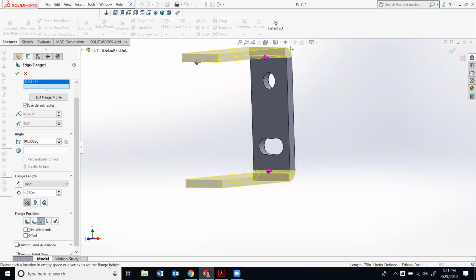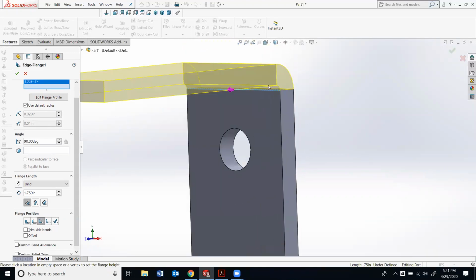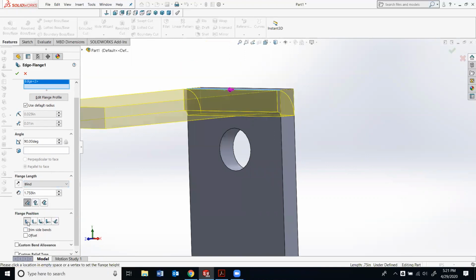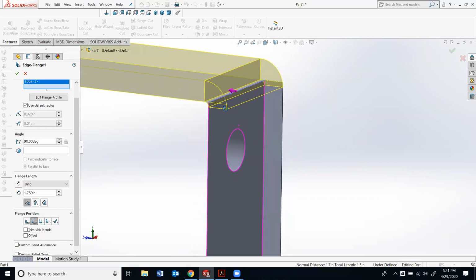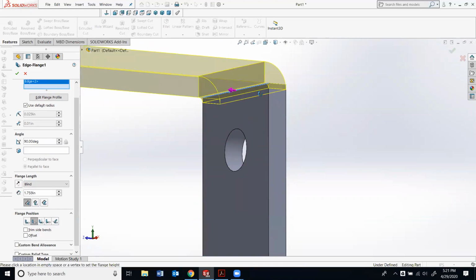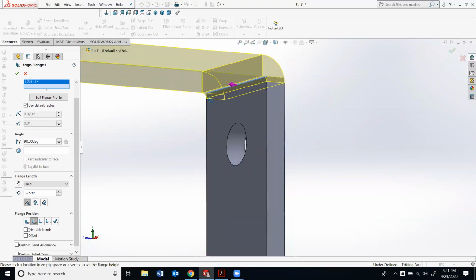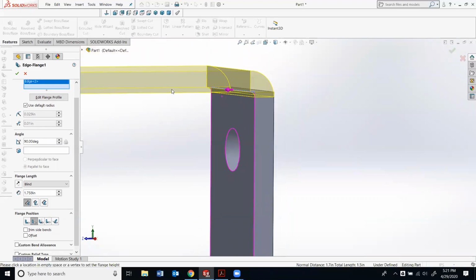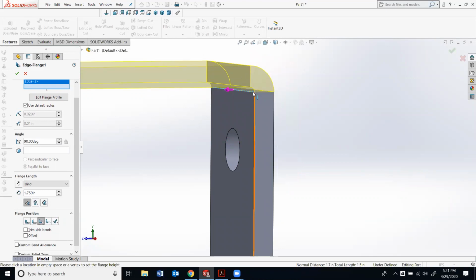So we can actually change or select where the bend happens. We could have it bend below, so like the top bend is there. We could have it so that the bottom of this part is the top. We have it so it starts bending at that spot and all sorts of stuff. So make sure we have that third flange position.